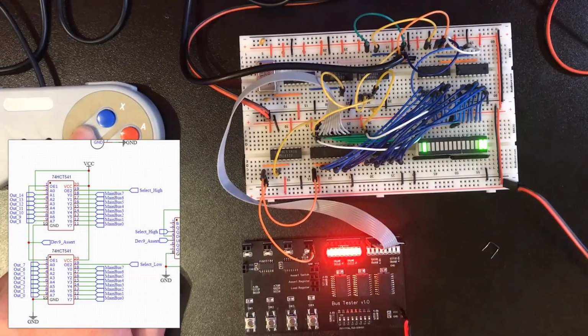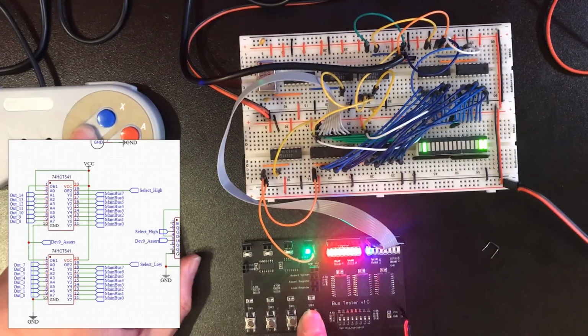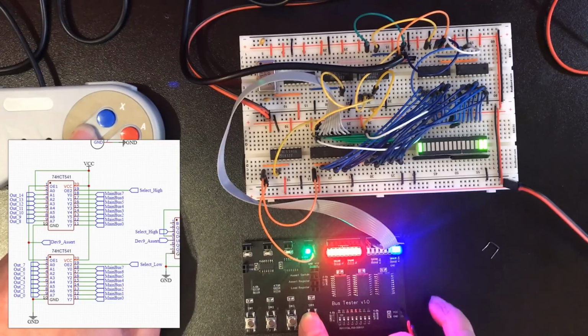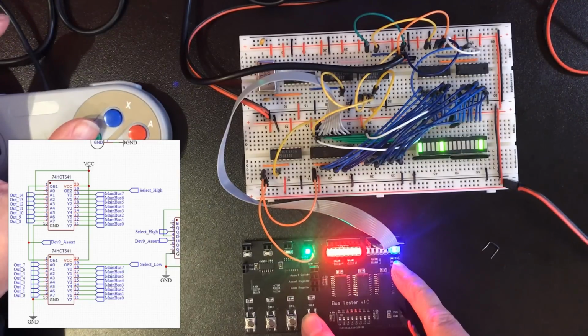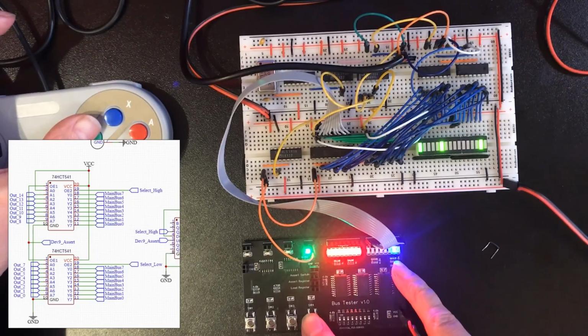Right, so we push a couple of buttons here, and that's outputting the high 7 bits plus our indicator, but then we load again, and it outputs the lower bits, which contain our 2 button status flags. Now I load, and we can see that left shoulder button, its bit is enabled. Load again, and I see the Y buttons bit is enabled.